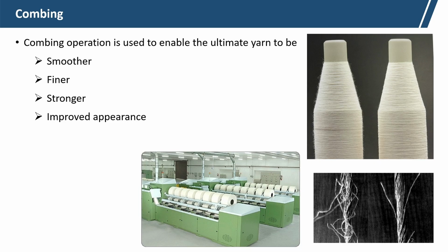Next is improved appearance. Yarn appearance will improve because of the removal of short fibers, and even if some small quantity of trash particles are there, they are removed.